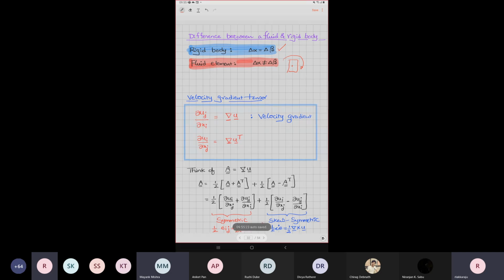So typically fluid elements always experience that shear deformation, compared to a rigid body kind of rotation. When we are going to learn about vortices, big cyclones, and so on, we will really come across how people quantify and simplify based on this deformation, to calculate where pressure is high, where pressure is low, and from where to where the cyclone migrates from one location to another. They try to quantify in terms of these elements. So there will always be two basic elements: rigid body rotation and fluid element deformation.